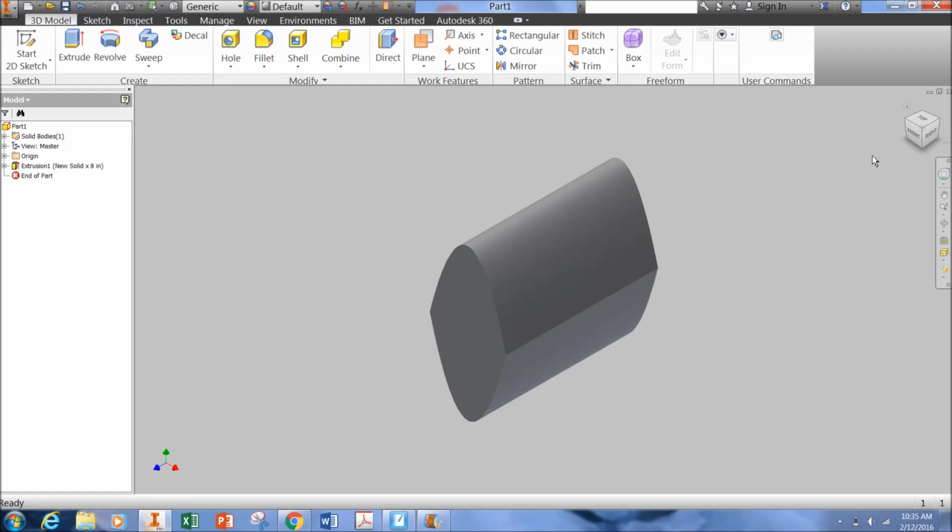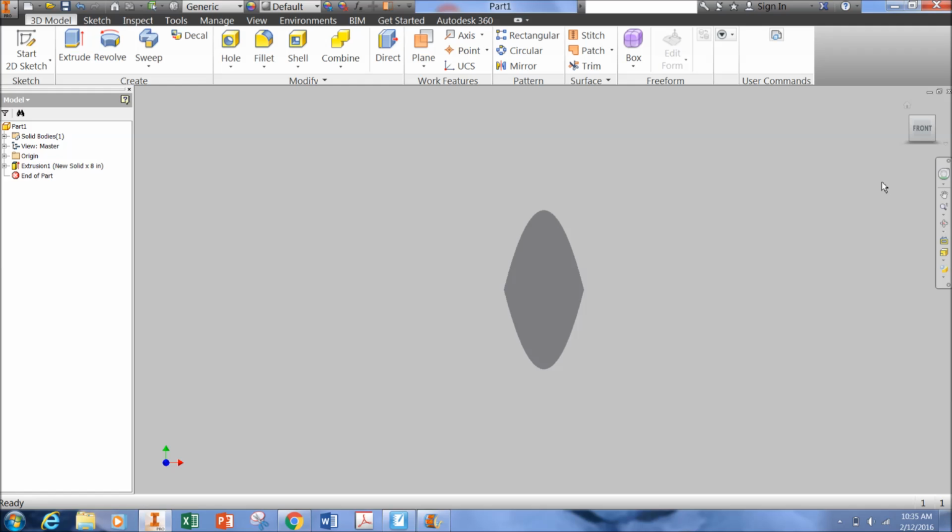By changing the orientation, we can see the base plane, which is the XY plane, and the two parabolic curves. We can also change to see the XZ plane and the height of the squares. Notice the height is constant, and we really want it to change as the distance between the two curves in the XY plane also changes. To do this, we must create a new equation curve, but on a plane perpendicular to the XY axis that passes through the points where the two curves in the XY plane meet. That can be seen right here.